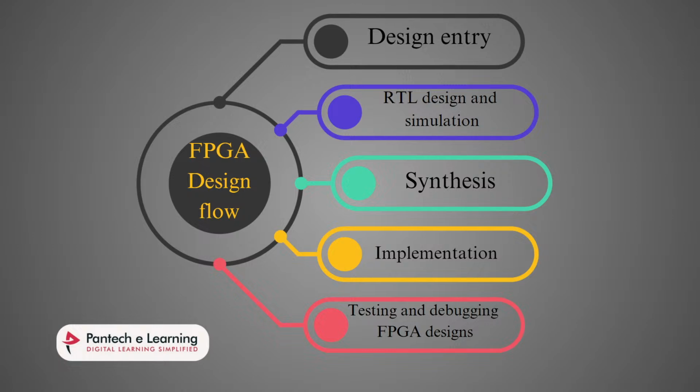First we have to write the RTL design for our circuit, and we have to write a simulation for that. The simulation is fully based on Verilog and SystemVerilog code. But in the current scenario, most industry people use UVM. UVM, used for simulation testing of the RTL design, stands for Universal Verification Methodology. RTL simulation tools like ModelSim, XSim and VCS are commonly used. The functional timing simulation made possible by these tools aids in early detection and correction of design flaws and performance bottlenecks. The next process of the design flow is synthesis.